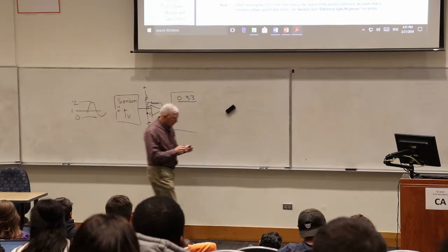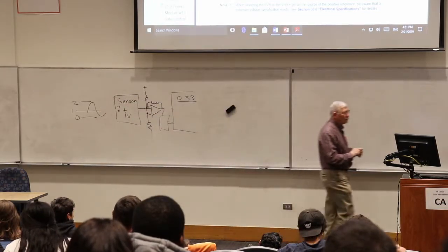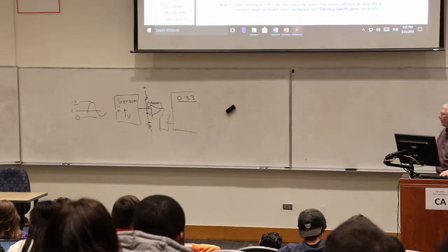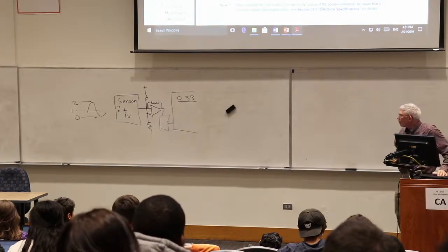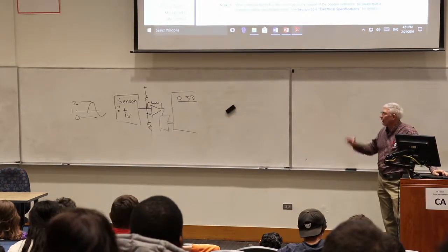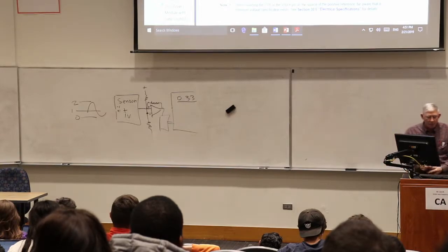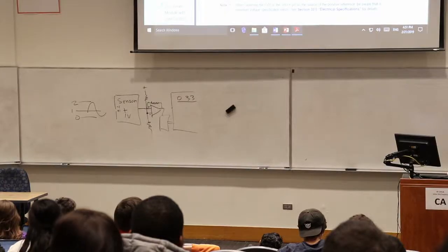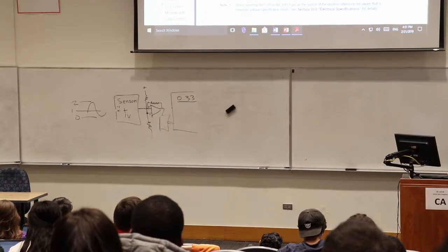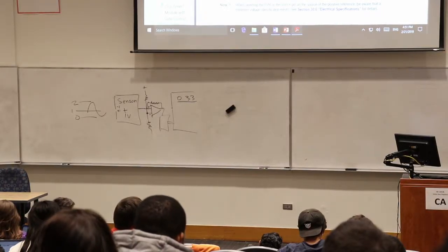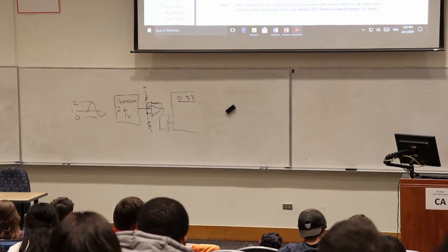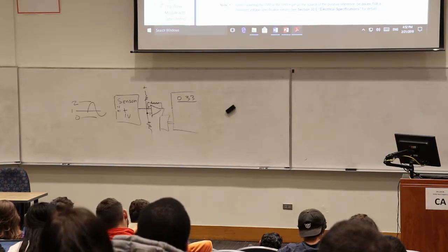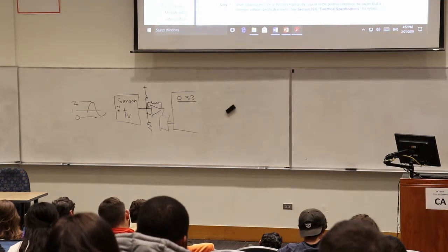So there's all sorts of features. You can certainly save money if you don't need real high bandwidth. But if you have to have something like video, oftentimes for video you're going to have some pre-processing because our micros may not be fast enough. Although some of them are, some of them will definitely handle video no problem. But anyway, very high speed, gigahertz signals that have to be demodulated, well, we might have to have a separate module for that. Okay. Any questions about how that's set up?